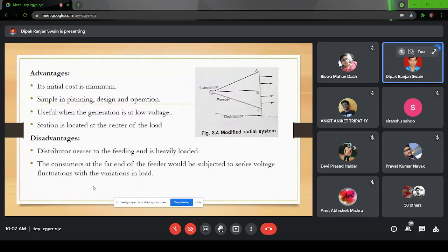Now, the main disadvantage of that is, let us say the distance is high. As I have told, you have gone from Bhubaneswar to Sundarpada, the next village. If the distance goes on increasing, what will happen? I am just talking about voltage. Let us say Bhubaneswar is at 11 kV. When it is going to Sundarpada, which is around 5 or 10 kilometers, it may drop down to 11.8 or 11.5 kV. Okay. Next village, there will be another drop. So it may come up to 11.2 kV.